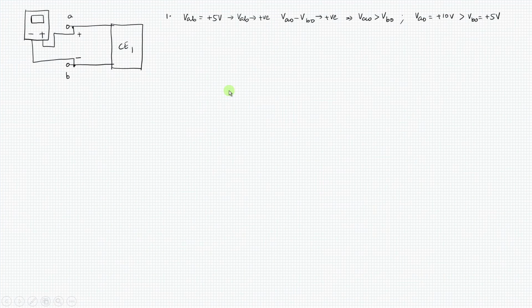An important thing that you have to understand while understanding all these concepts is that, even if I did not connect this multimeter here, because of this circuit behavior, there would be a polarity which is existing here. And it is that polarity and magnitude that you are trying to measure with the voltmeter. The voltmeter is not creating the plus 5 volt here, right? The circuit is creating the voltage and a particular polarity. You are only trying to measure that value using the voltmeter.